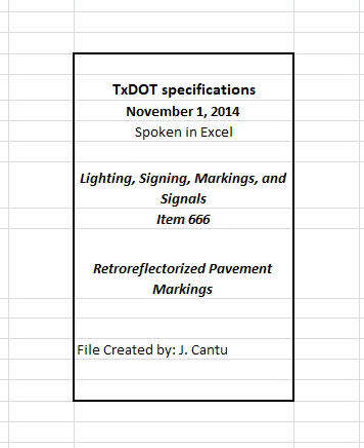Using widths and colors shown on the plans. At locations shown on the plans. In proper alignment with the guides without deviating from the alignment more than 1 inch per 200 feet of roadway or more than 2 inches maximum. Without abrupt deviations. Free of blisters and with no more than 5% by area of holes or voids. With uniform cross-section, density, and thickness. With clean and reasonably square ends.